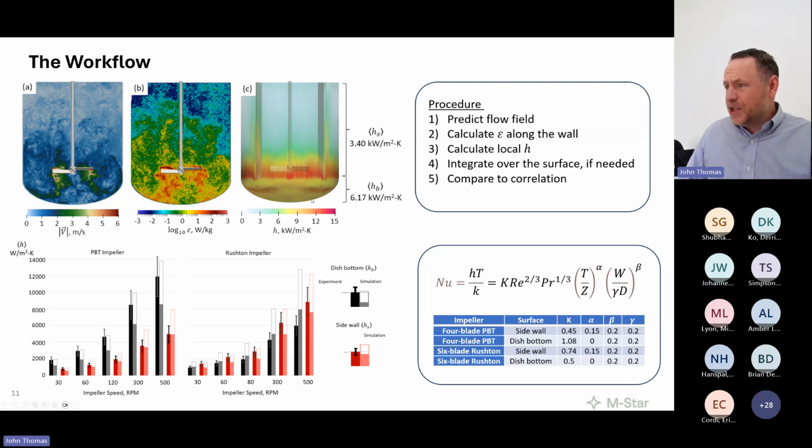If we can get this right, it gives us confidence that we can get even simpler systems moving forward. And so foundationally, here, for example, is a standard off-the-shelf correlation for predicting Nusselt number. We're not using this in M-Star, but we're going to use it as the comparison, because it's very well validated, against what we're predicting using this semi-empirical first principles approach. This is a system-level correlation. In M-Star, we have the local variation. We can then recover and integrate to predict the total system-level response, but we're arriving at that system-level response by analyzing the discrete behavior as opposed to jumping straight to the system-level behavior as would be done in a correlation. That's okay, the correlation is great. But let's see how well this general approach holds up in these very spatially varying systems.